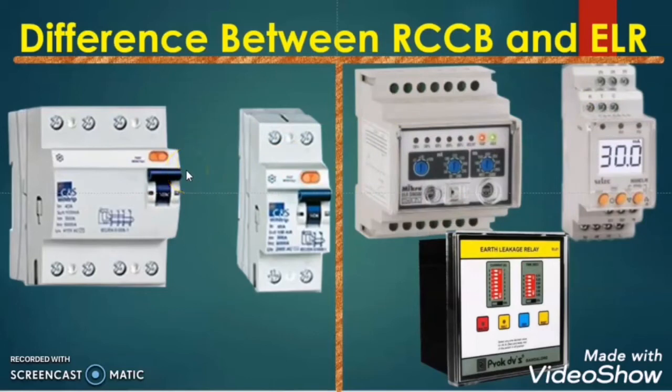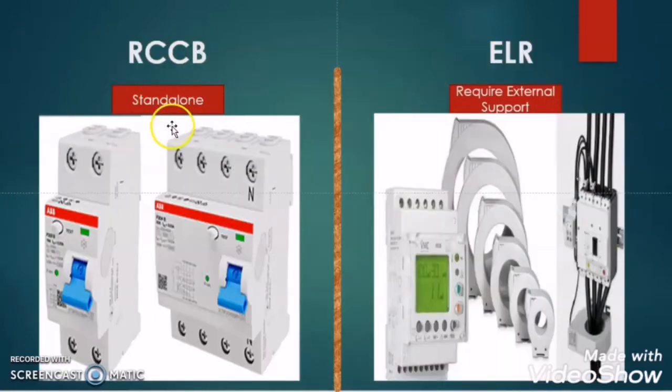Now let us take, one by one, the differences between RCCB and ELR. The first difference is that the RCCB is a standalone device, but the ELR requires some external support to work. What does it mean? Suppose an earth leakage fault happens at the load side. Then the RCCB will sense it and trip itself.